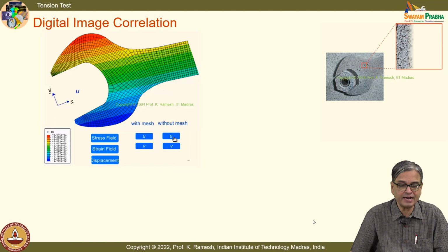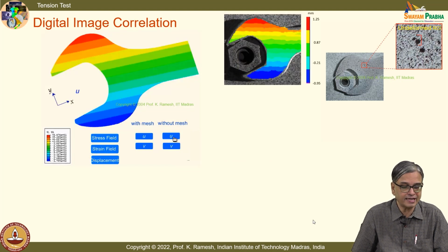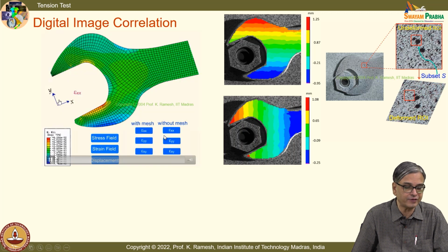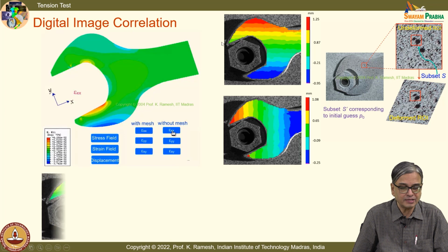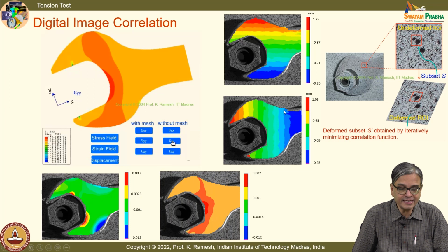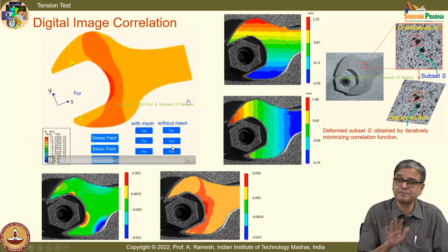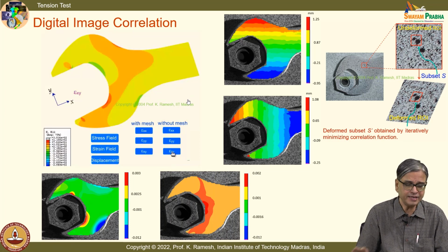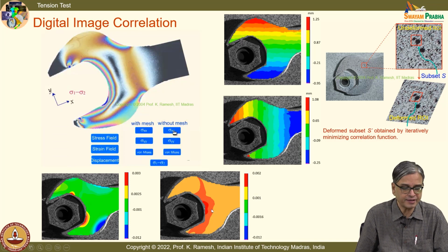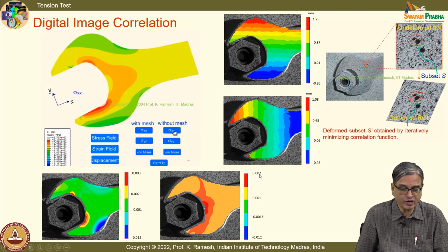And this also compares, what is the result I get from finite element and what is the result I get from image correlation. See, finite element I have used a different reference axis. So, these things have to be rotated, that is not done here, but the idea is you see similar patterns in displacement. Displacement measurement is reasonably good, fine. But when I compare the strain, the accuracy is not very high, okay,